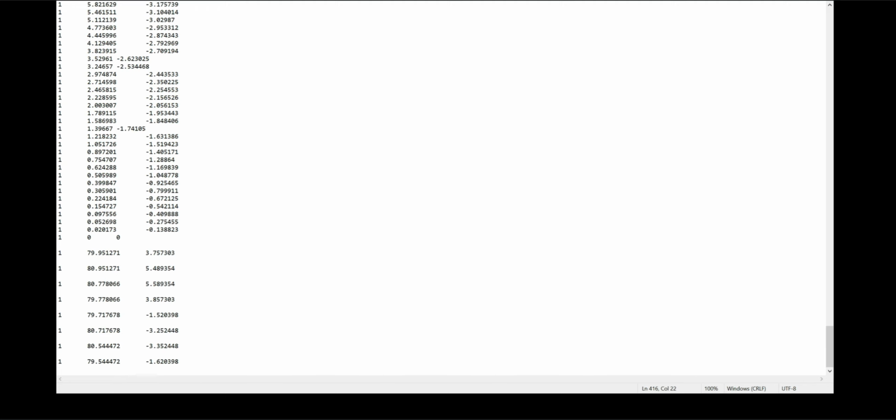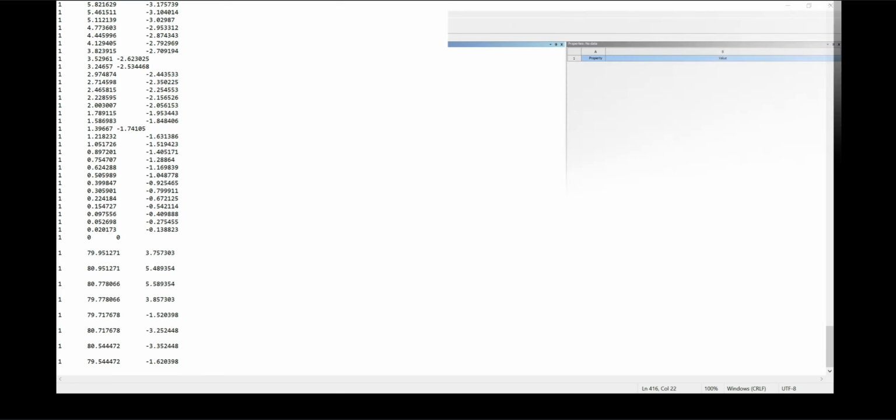Let's go with the first method as recommended in the ANSYS help documentation. Oh, and one more thing. SpaceClaim 2D doesn't use z-coordinates, so make sure to remove that column first. Now, copy all the data and paste it into a new Notepad file. Save the file, then open ANSYS Workbench.